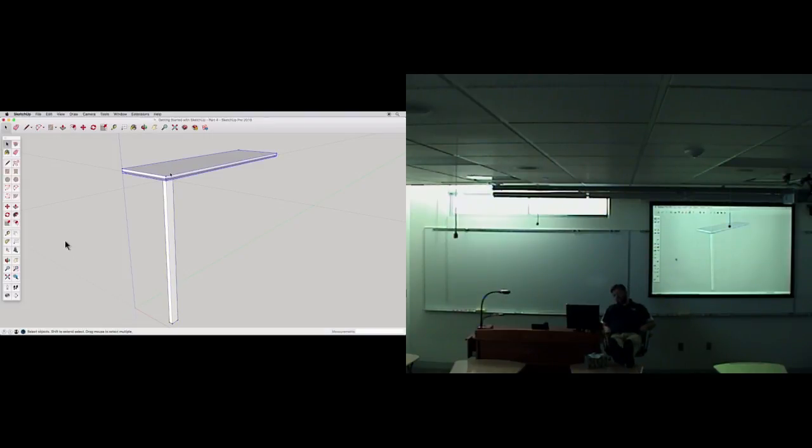A group or component binds the geometry together into a single entity. You can move, rotate, and scale the group as a whole. However, a tool like push-pull doesn't seem to work because you aren't affecting the actual surfaces, but the whole group together. To use push-pull and other tools, you need to edit the group.